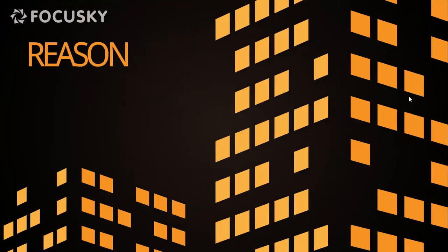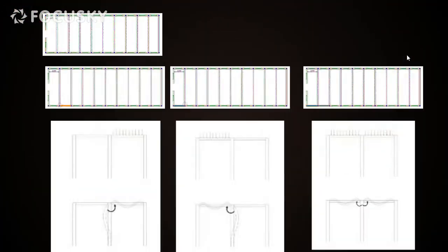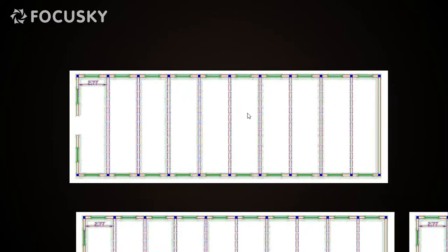With this in mind, we'll move on to the column orientation. To study the column orientation, we'll take an example of a hall which is 30 meters in length and 10 meters in width. The hall is divided into 10 equal bays. So let us study this column for column orientation. Assume that the beam which is on the right hand side of the column alone is loaded. All the other beams are not loaded.